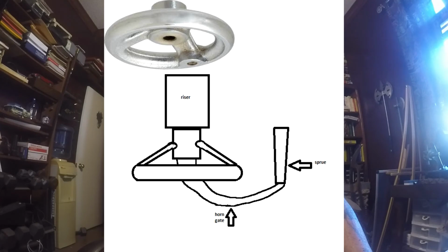Because the hub in the middle would be smaller, it would automatically start to solidify before the riser ever did. And then once it became solid, you would still have some molten metal in the riser, and it would start solidifying. And then on the very top of the riser, whether this be a blind riser or a riser open to the atmosphere, the piping would take place, something that you expect.